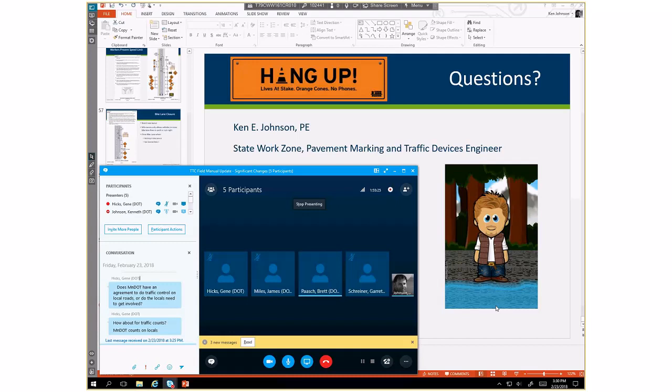The problem is when there's not an adequate parking lane to even get a sign on a stand in. So I think it's something we'll have to kind of fumble our way through until we can get it right. Another alternative to this is doing post-mounted signs. It's kind of a hassle to do them, but as long as you put a post-mounted sign that's 7 feet at the base, you don't have to have a detectable edge around it.